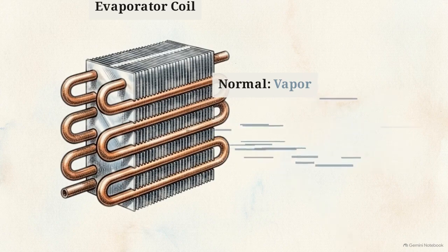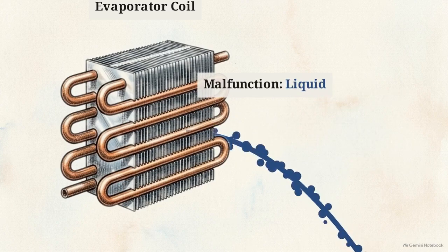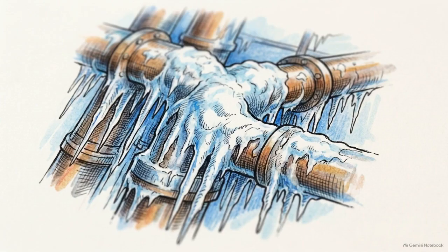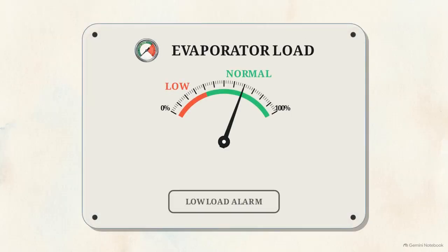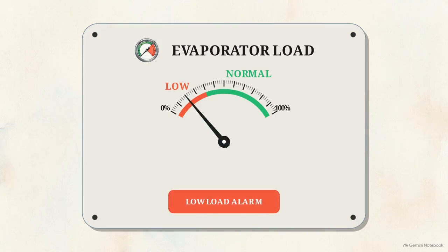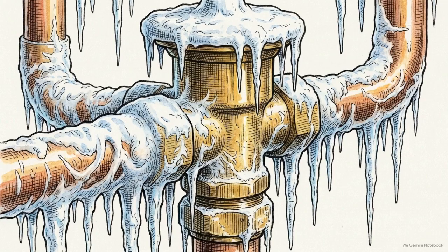When transient liquid refrigerant fails to evaporate and exits the cooling coil, the system enters a failure state known as floodback. This occurs when system variables fluctuate, specifically during periods of low evaporator load or when the expansion valve fails to maintain correct superheat parameters.